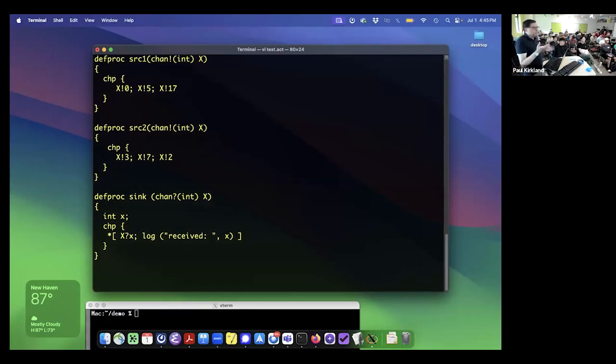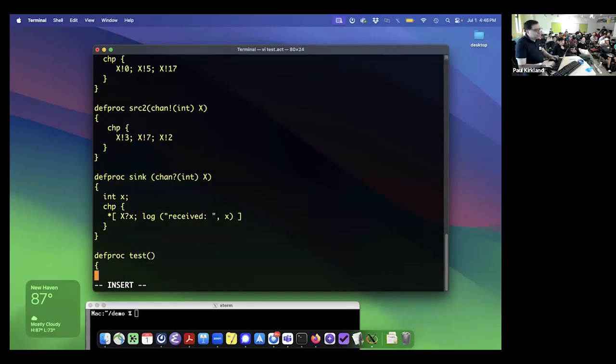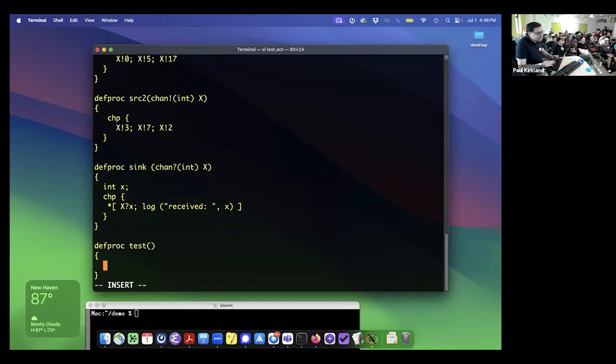We've even got a RISC-V core, which we synchronize with Spike to make sure that cycle by cycle, we have the same register file state. Yes, this is not really a joke, it's true. We wrote this language to design chips, not to write papers. So it has all the things you would need as a designer, and if there's something really important that's not there, we add it. Okay, so now I need to wire stuff up. I think I had an adder, let's call it A. There's lots of flexible syntax for connecting things. I'm going to show you the lowest level syntax.